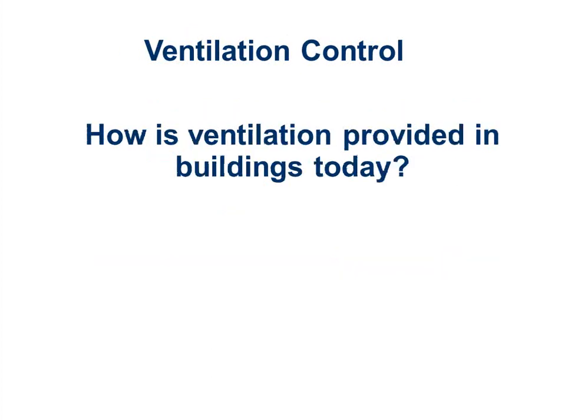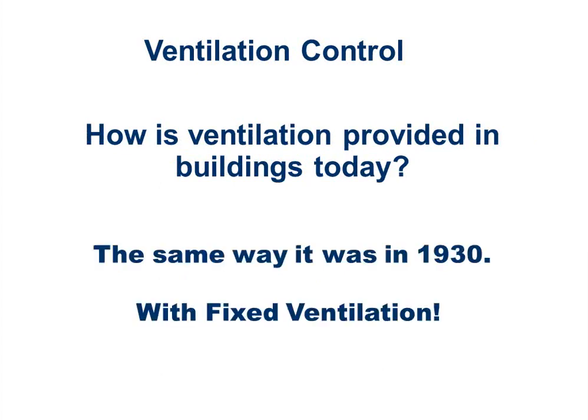The way we ventilate most buildings is the same way that we've always ventilated buildings. We basically fix the outside air louver to a locked position, and then we leave it there all the time. Hopefully, at least at nighttime, we shut it. But we don't modulate it. We don't track what's going on and what's needed in the space. We just put it to some very high position, which overventilates the space, and we feel we're pretty safe and we're covered.